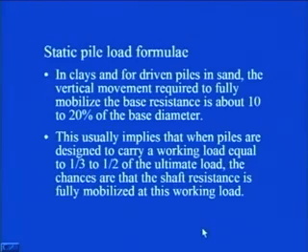See, the ultimate load is calculated using the static pile load formulae or any other measure, then it is halved or taken as 1/3, and then the structural design of the pile is carried out using this halved or 1/3 of the ultimate load.